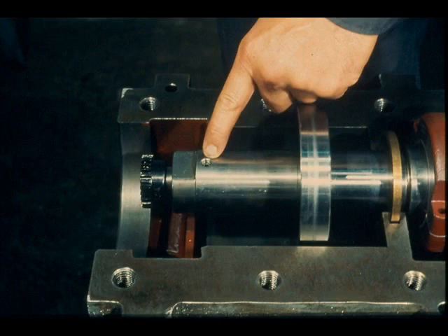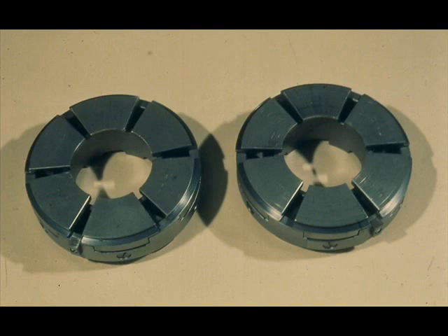We mentioned earlier that the thrust collar was locked onto the shaft with a lock nut that we can now see here. The lock nut is then secured to the shaft with a lock screw being pointed out here. Now, let's take a look at the thrust bearings in detail as shown here. Remember, there are two thrust bearings in this assembly, one active, one inactive.